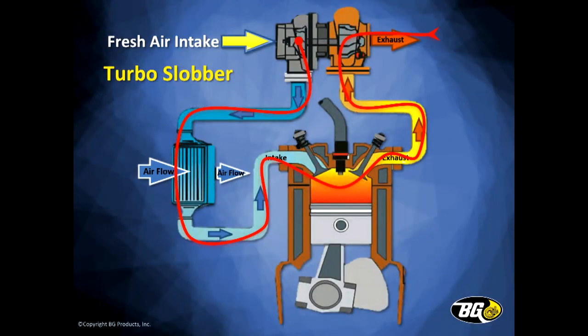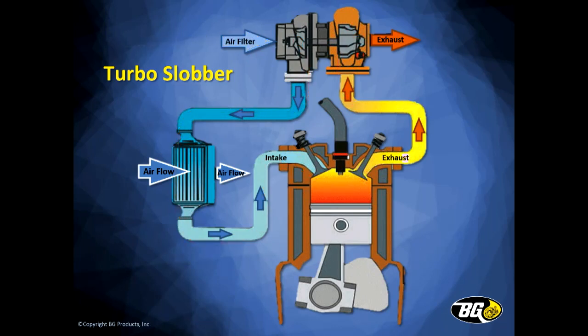So this turbocharger itself has got one impeller located in the intake, one impeller located in the exhaust. On the intake side, you've got an impeller wheel, and on the exhaust side, you've got the turbine wheel. These two wheels are hooked together through a shaft, and that shaft itself rotates. It can rotate over 125,000 RPMs. That's high speed.